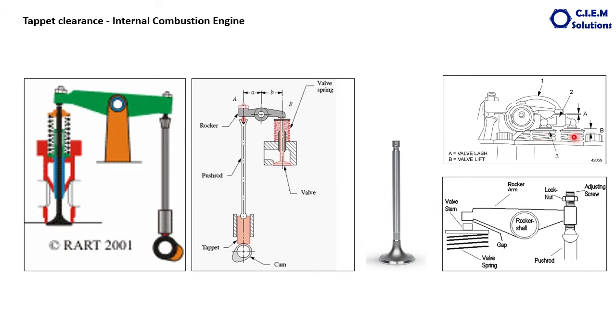To open or close both of these valves simultaneously, another device is provided, known as the crosshead. This is the crosshead, which sits on both valve stems. Over and above it the rocker arm sits, pressing this crosshead. In turn, the crosshead presses both the valves simultaneously. So here the valve lash has to be maintained.